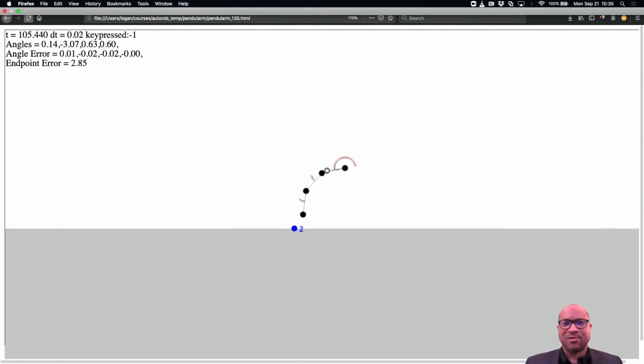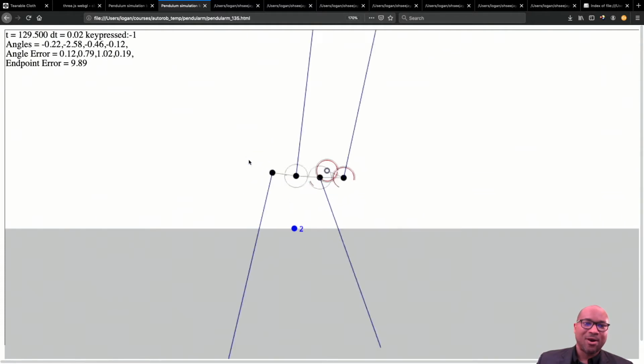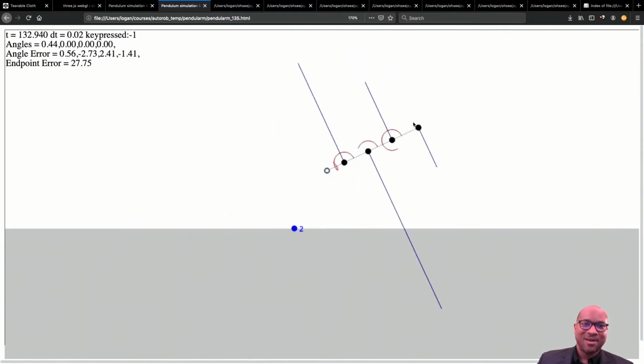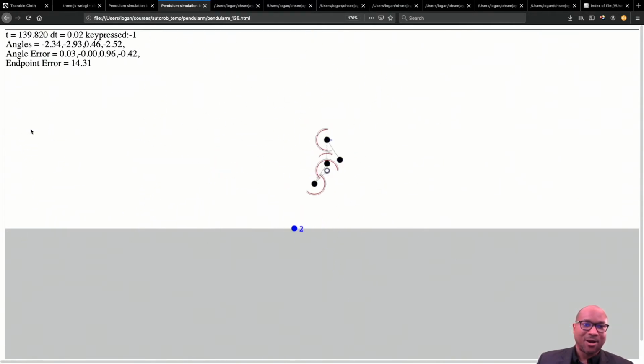And so I can make this really fast. I can implement this really quickly. I just can't necessarily ensure that I'm going to obey many of the physical laws. Similar to that, I can do certain things with this that might be difficult in generalized coordinates. If I click on a part of my robot, because it's just springs, I can stretch it out and move these in different ways. I can just move my robot arm and then let it go, and you can see the springiness of it. I can also, like with my generalized arm, just turn off the servos and then bring them back up.